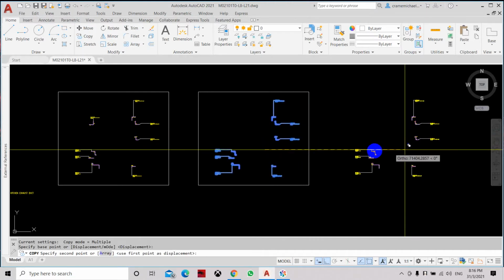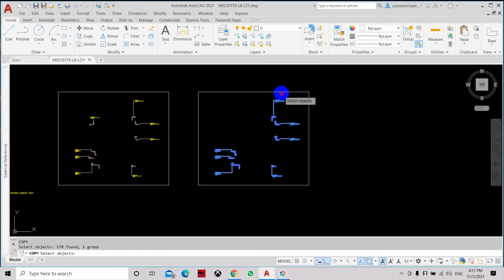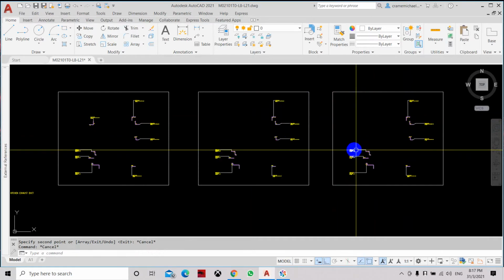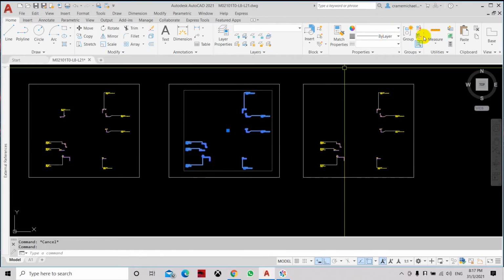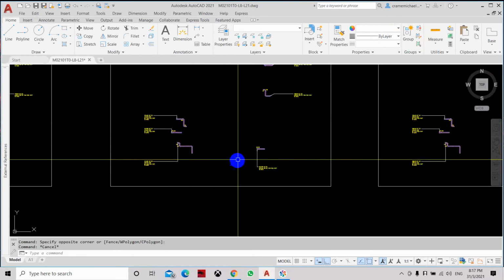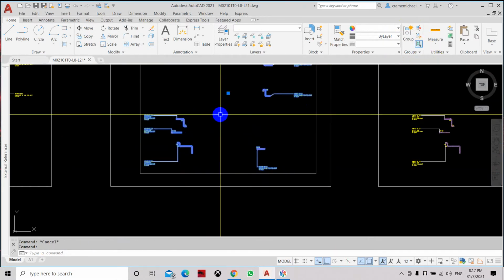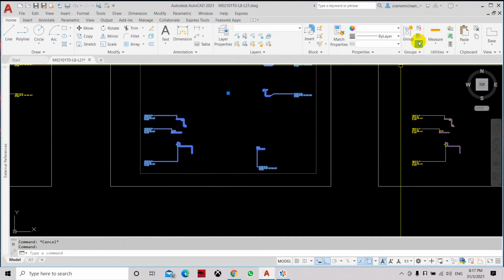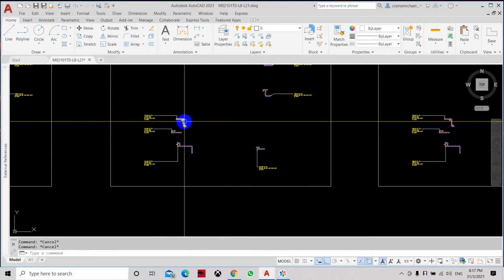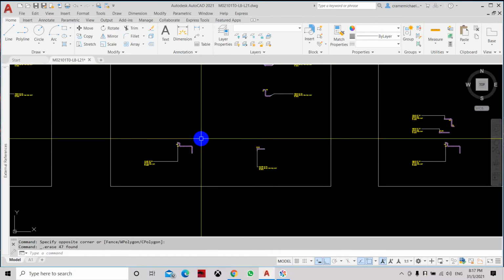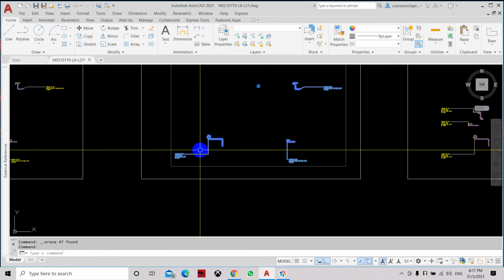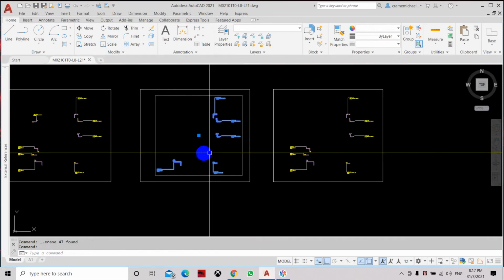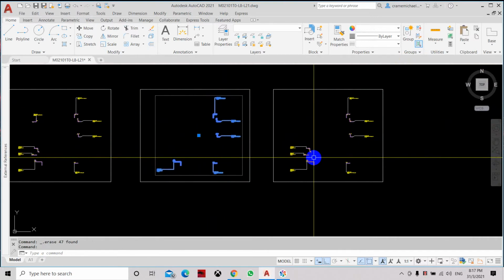Let's create the copy including the group and the box so the difference is easily seen. Let's say here is a group object and I want to edit this and just turn off the group selection for this object. You can just edit it, and then we can select each individual item here. We also save. Now let's click back the group again. Here it's grouped together, but we have edited this part of the group objects, while this copied group object still maintains the same. So that is the difference between the group command and the block command.